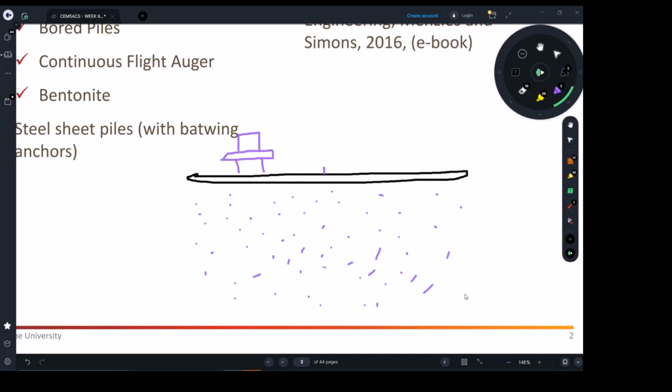They say definitely you have to use driven piles. You can't just enhance and prepare the soil. They will give you all those pieces of advice. So what we do in this case, say after 6 meters here you've got a proper soil, maybe that clay I was talking about, we have to nail in driven piles, with the techniques I was talking to you about.